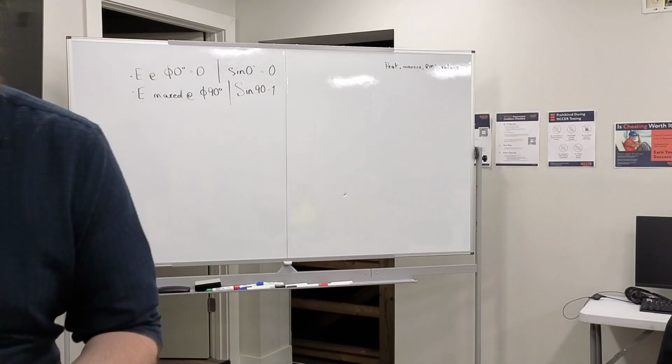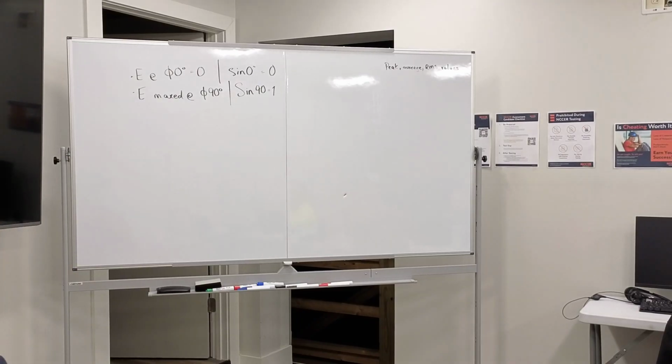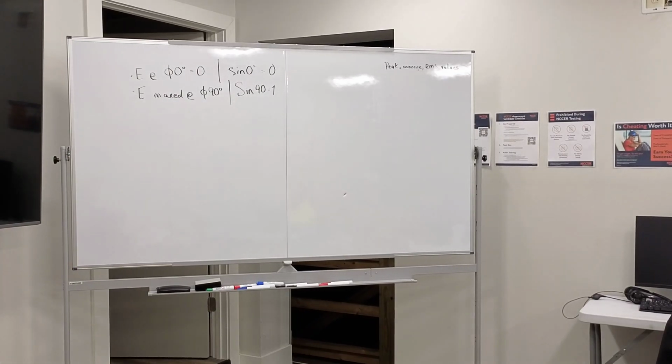Your stuff's packed through the neutral. The neutral's technically a hot. It's just half of a phase, the extra voltage. No, the center tap. The neutral is technically still hot, it just has no potential. It has no potential because it's grounded. So it has no potential difference between itself and the ground. But it still carries current.